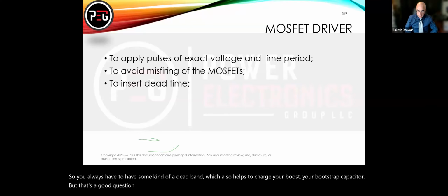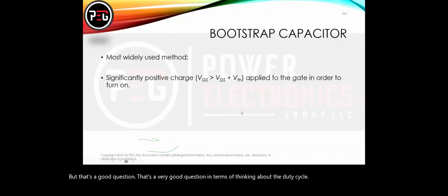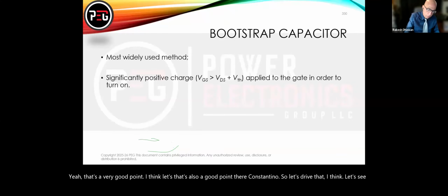That's a very good question in terms of thinking about the duty cycle. Is the bootstrap capacitor charged when there is the dead time? I believe it is going to be charged when you have the low MOSFET on. Yeah, that's a very good point, Constantino. So let's drive that. When does the bootstrap capacitor get charged? Let's think about that for a second here.